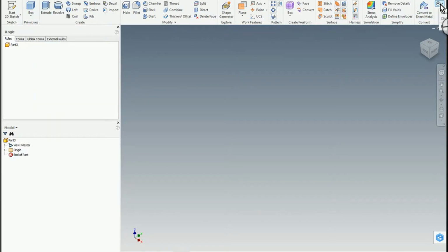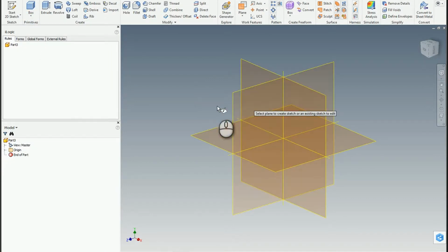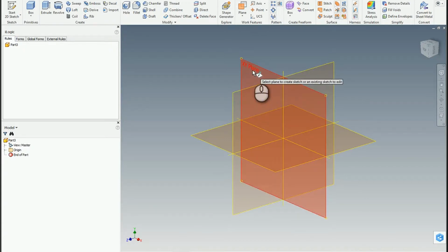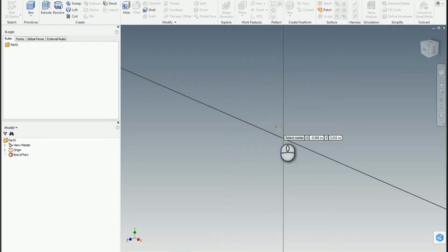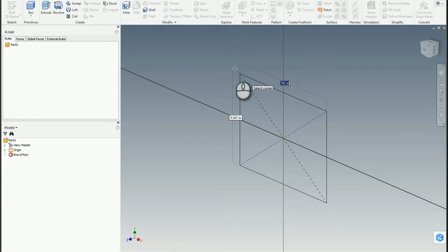So if you come over here, if you're not familiar, you can't see your primitives, you choose this tool. I'm using Inventor 2017. And you click and you just find the primitives. That should stick it over here towards the left. And I'm just going to build a simple box. If you don't see the box, just hit the drop down and find the box icon like so. And then again, we're going to treat the z-axis as our up axis, positive z, so I'm going to use the xy plane. And I'm going to use the center point rectangle that's automatically used.